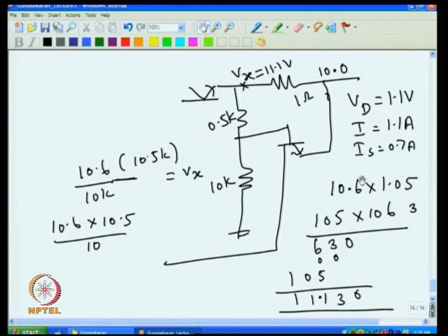So if you remember it as a reverse bias and follow this example, it will be very clear that fallback current limiting works depending upon the voltage across this. So one can alter these two resistances to get the required short circuit current. So this is about short circuit protection given to the voltage regulator.